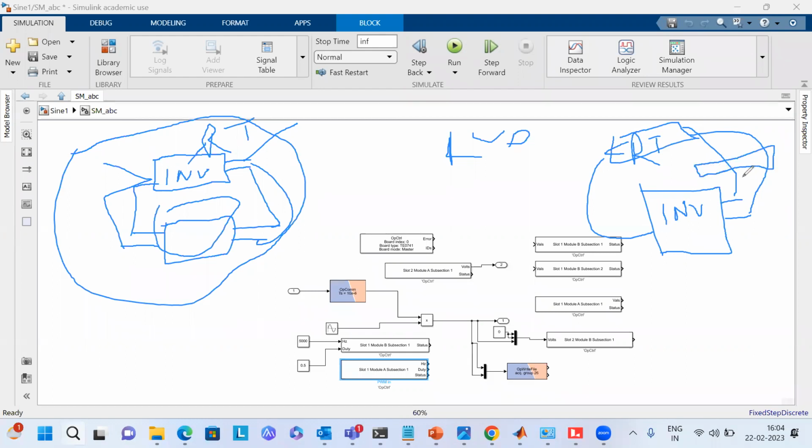We need to step down this voltage and current. Our product is OP8662. We can use this OP8662. With it, we can measure up to 600 volts and 25 amperes. Directly connect your inverter's voltage and current here, and connect it directly to your OPAL-RT, and you can control your inverter directly.